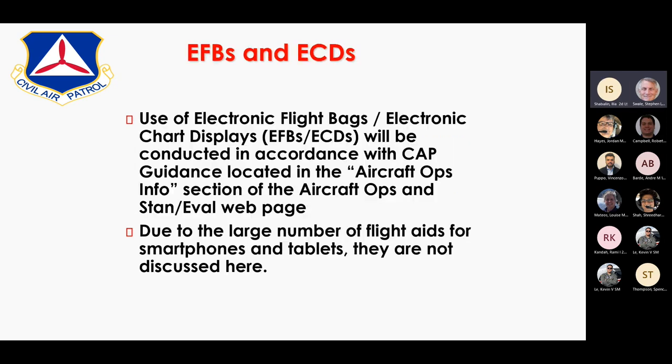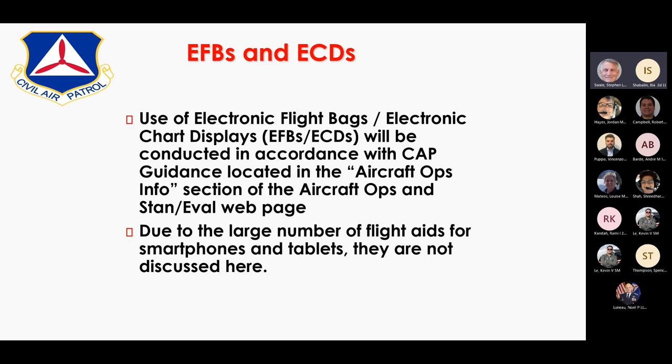Use of electronic flight bags. We've already gotten the pitch that if you're a VFR pilot in CAP, you get ForeFlight. I used to use another electronic flight bag by Seattle Avionics that I was getting as a freebie as a CFI. I absolutely love ForeFlight. It's got CAP grids available on it. It also has the ability to display TFRs, which is very important for us during fire season in California, to have the TFR automatically shown to you on the equivalent of a sectional is really important if you're flying to the TFR to do Waldo photo missions.